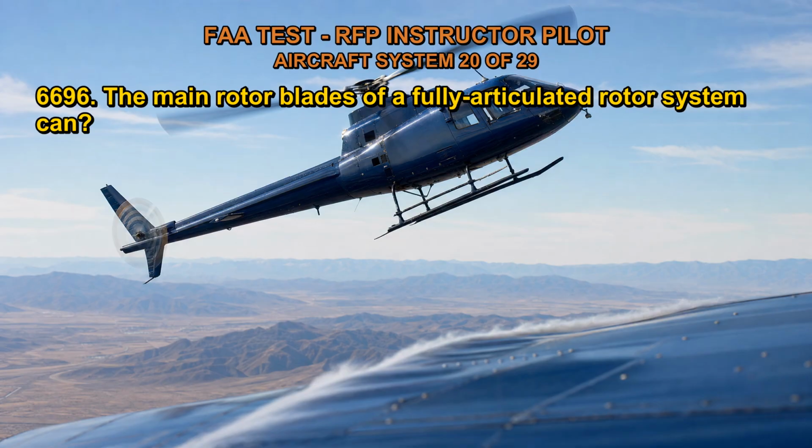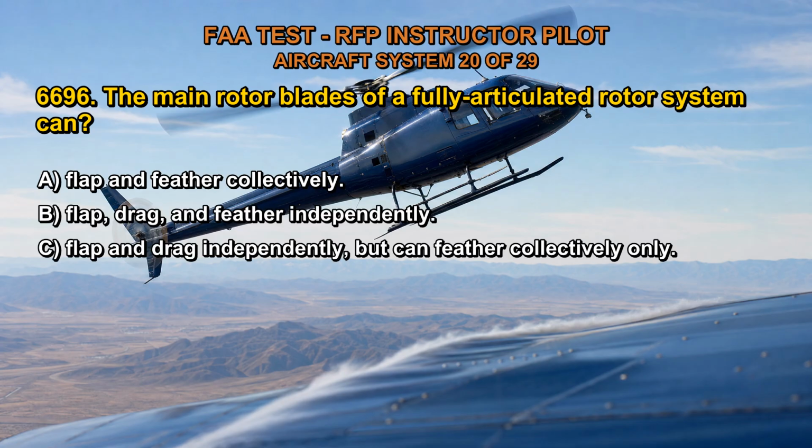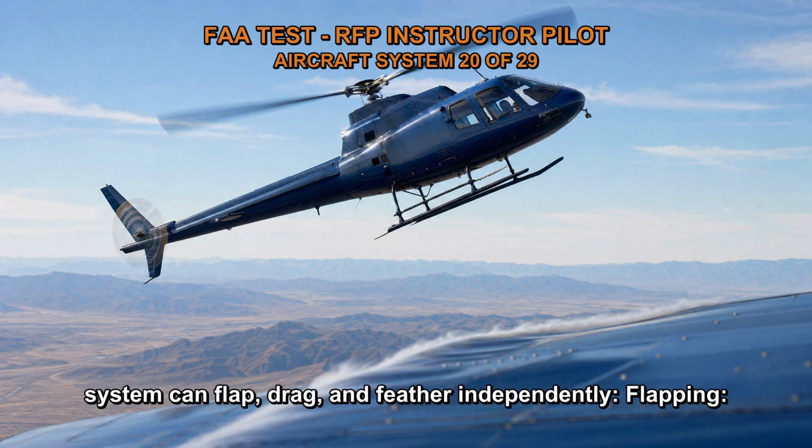6696. The main rotor blades of a fully articulated rotor system can: A. Flap and feather collectively. B. Flap, drag, and feather independently. C. Flap and drag independently, but can feather collectively only. The correct answer is B. The main rotor blades of a fully articulated rotor system can flap, drag, and feather independently.